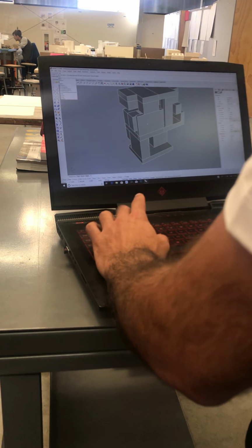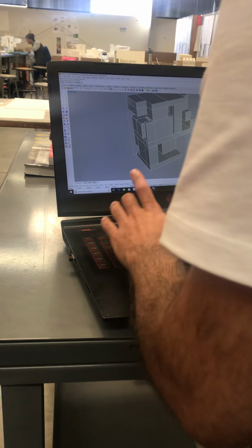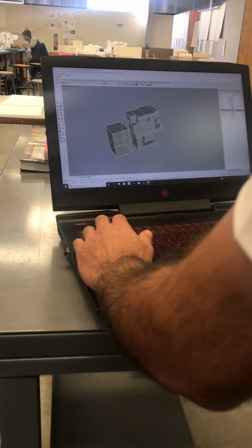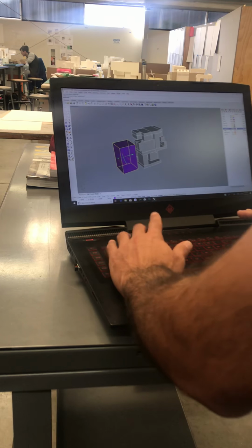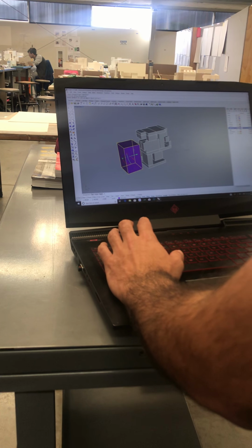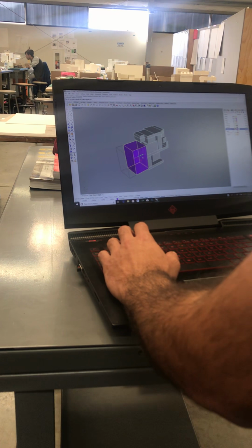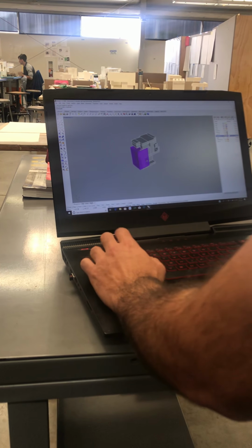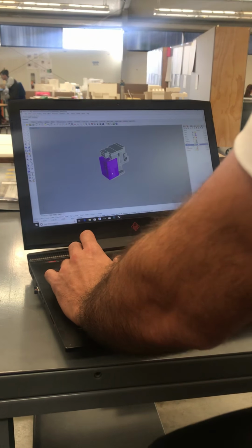I'm just gonna go through and make my box. 6 inch by 6 inch by 9.5. And there's my box. And I'm going to put it on the subtraction layer or just another layer. And then another thing I want to do just to make it easier for myself is type in this command called set object display mode and hit enter. And then when I go to mode, I want to select ghosted. And now this box is ghosted while the other one isn't. So if I move it over this box, I can see through. Set object display mode, then hit M and then select ghosted.